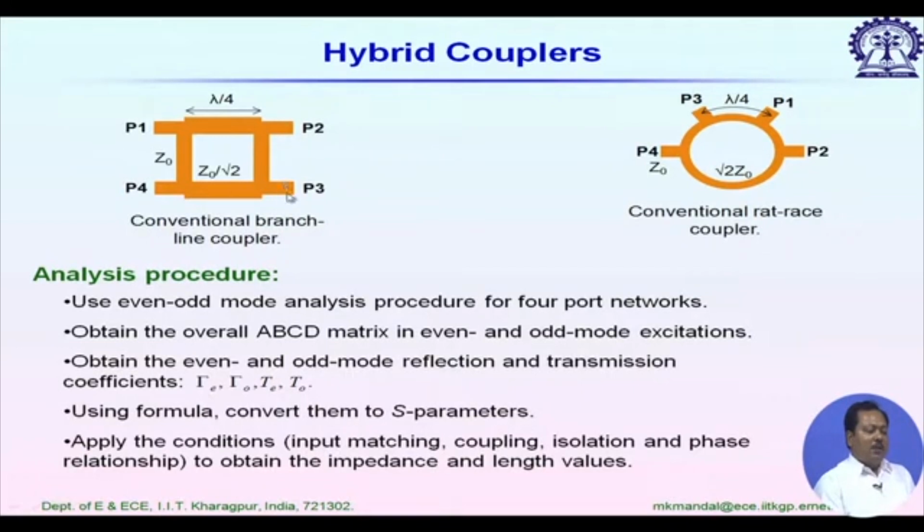If we have equal power splitting, and we solve using the required criteria of S parameters, it can be shown the length of each arm at resonance frequency should be lambda g by 4, where lambda g is the guided wavelength, and the characteristic impedance of the top and bottom line should be Z naught by root 2. This is for equal power split.